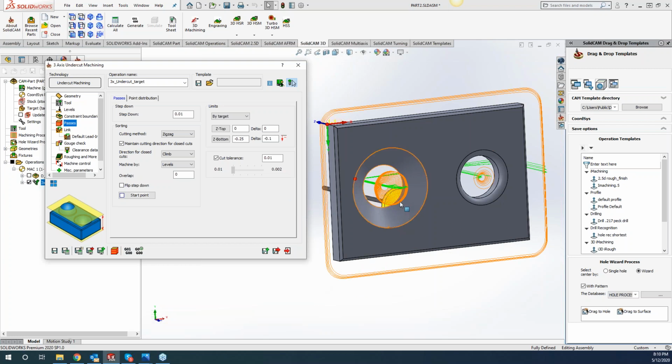Okay, so now we're able to attack 3 different surfaces, well actually 6 different surfaces, all with one toolpath, where before to achieve this in HSS, you would have to have 3 independent operations to get this job done. Like I said, this is more geared towards multiple undercuts on a mold or any kind of part that you guys are looking to do.